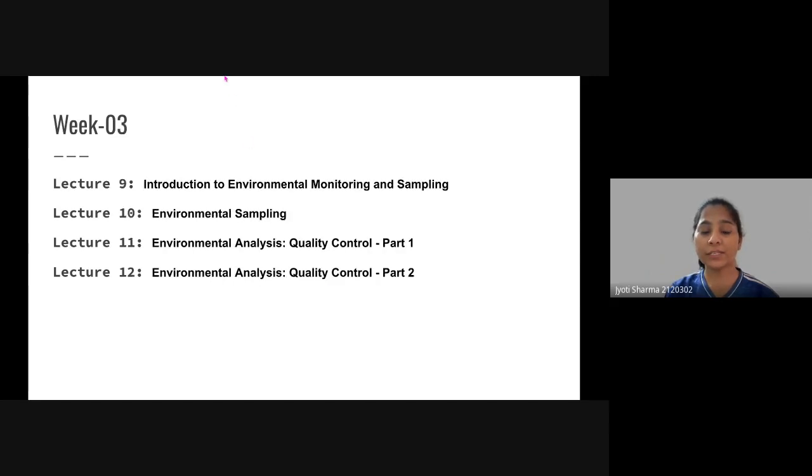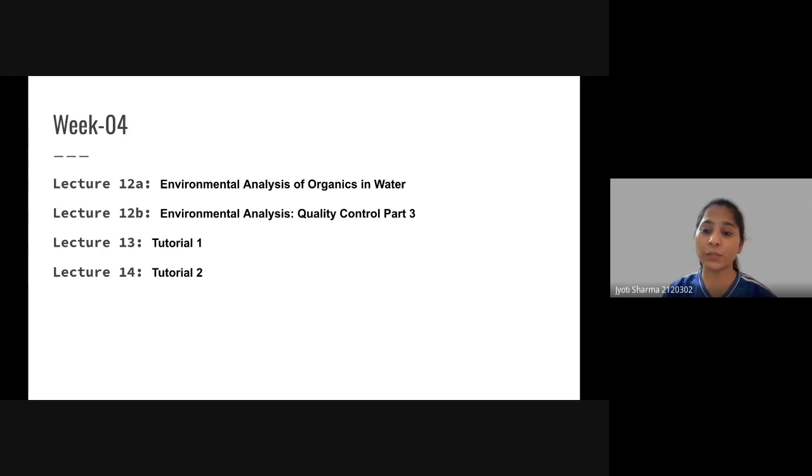Then we moved to week 3. This was environmental monitoring and sampling, in which we discussed quality, precision, and accuracy. If you are doing any test, what is your confidence that whatever test you have done is correct or not? We learned about these terminologies in week 3. In week 4 we started with the analysis, where if we want to extract an organic from the water, again let's say benzene, then we have to extract it in a solvent. That solvent should be organic in nature.